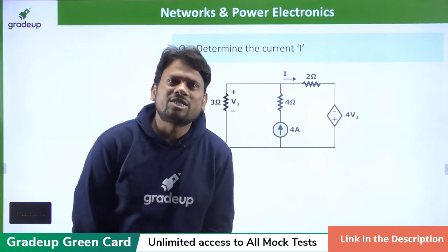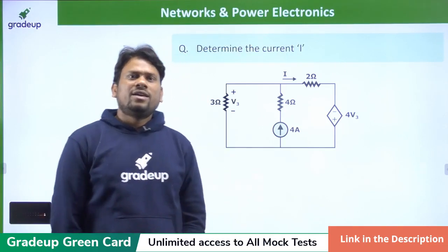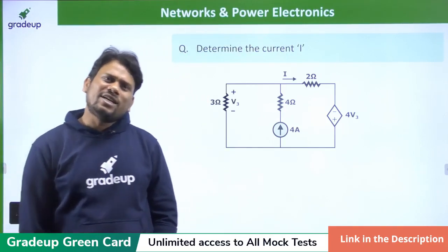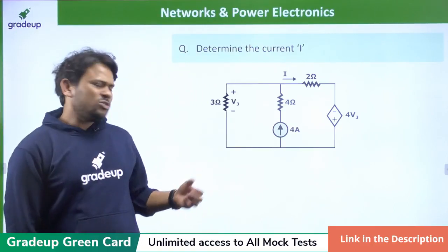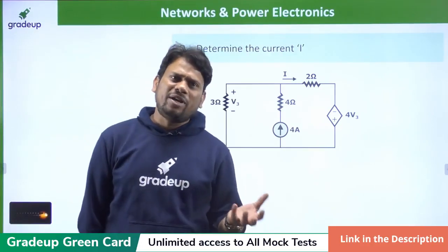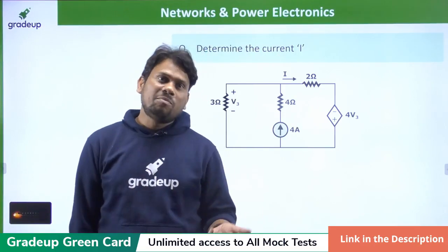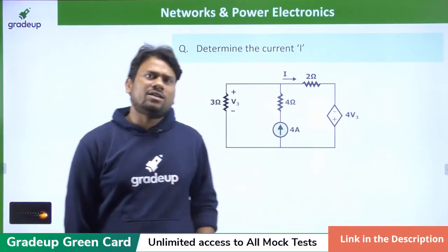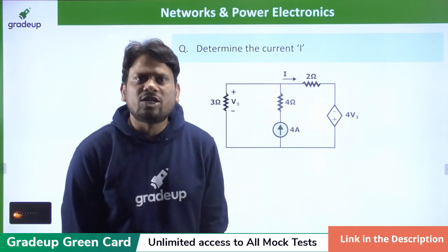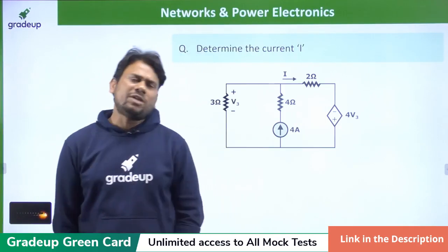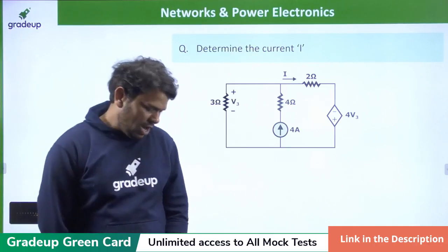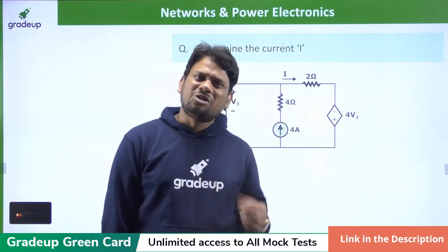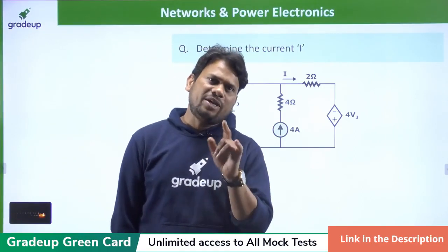Again, I am going to discuss one doubt from Shivam Rana. My dear friend, BJT has a negative temperature coefficient. We don't have too much time, so I can't explain that type of thing in detail, but I'm giving you some idea. BJT has a negative temperature coefficient. What is the meaning of negative temperature coefficient? You should know well. Now negative temperature coefficient introduces the secondary breakdown problem in the BJT.